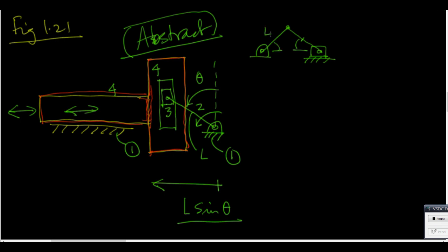Okay, so if this is L1 and this is L2 and this is theta and this is phi, there is only 1 degree of freedom. Theta determines phi. So phi is known in terms of theta. Let me write phi of theta to indicate that. This distance is equal to L1 cos theta plus L2 cos phi of theta. Okay, so it is no longer purely sinusoidal because phi depends in a complex way.